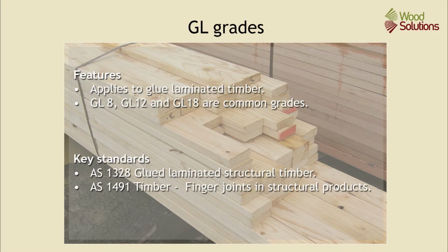GL grades apply to glue laminated timber sections, as the letters GL are shorthand for glue laminated. Common grade terms include GL8, GL12 and GL18. The key standards covering GL graded material are AS 1328, glue laminated structural timber, and AS 1491, finger jointed structural timber.